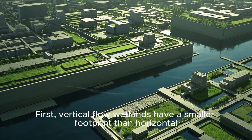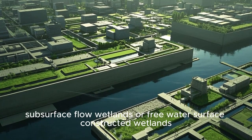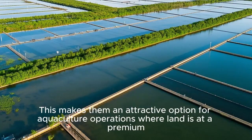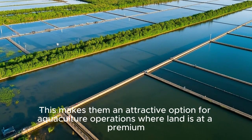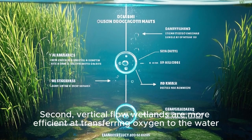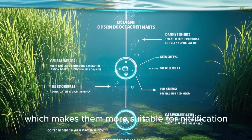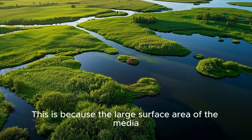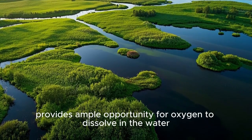First, vertical flow wetlands have a smaller footprint than horizontal subsurface flow wetlands or free water surface constructed wetlands. This makes them an attractive option for aquaculture operations where land is at a premium. Second, vertical flow wetlands are more efficient at transferring oxygen to the water, which makes them more suitable for nitrification. This is because the large surface area of the media provides ample opportunity for oxygen to dissolve in the water.